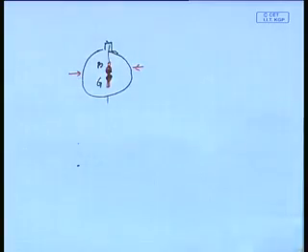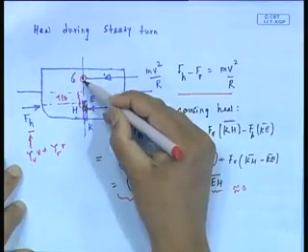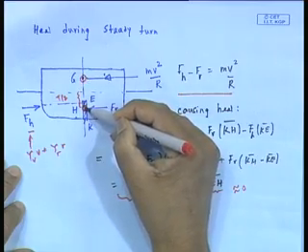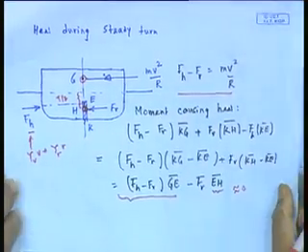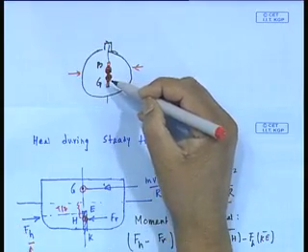Compare that to this, or what we have done in this other one. See here, my G point was above the point of action of the hull forces, but for a submarine, typically, because of stability, my center of buoyancy has to be above the center of gravity.